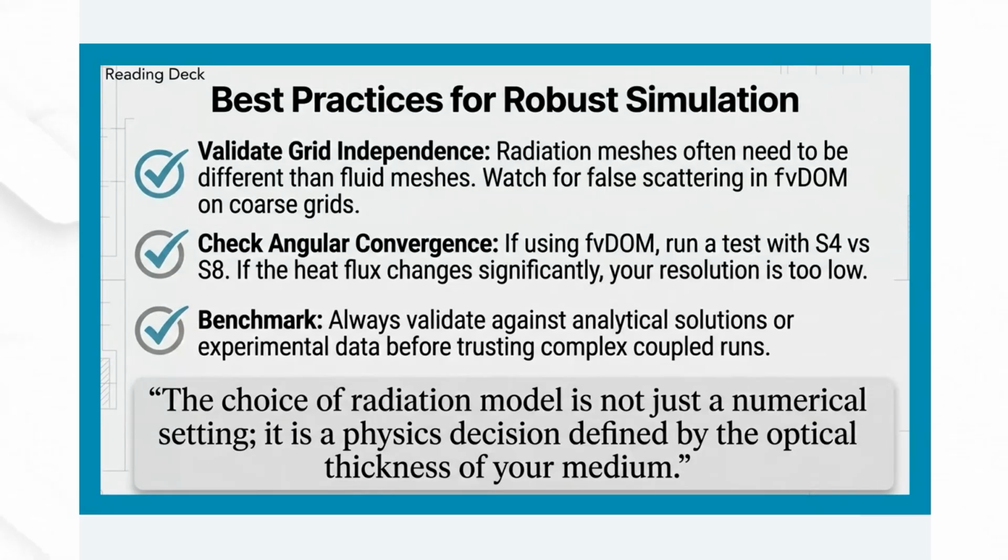Then it comes to the point where you need to keep increasing the angles until you see this result change, essentially. And finally, never trust complex coupled equations blindly. Always benchmark your model. Before simulating a full battery pack fire, actually simulate a simple block with a known temperature. Check this against your analytical or experimental data to ensure that whatever model you've used is physically realistic.